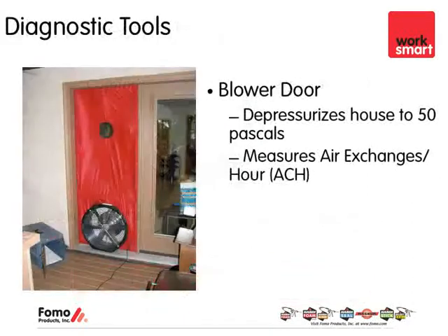First off, the most prevalent of anything would be the blower door. This is the most significant diagnostic tool. The blower door really allows a contractor to simulate a house under worst case conditions, and in this case, worst case conditions really might only be simulating something similar to a 20-mile-per-hour wind hitting the house. So what they do is close all the windows and doors to the house on the exterior. They open up all the doors in the interior.